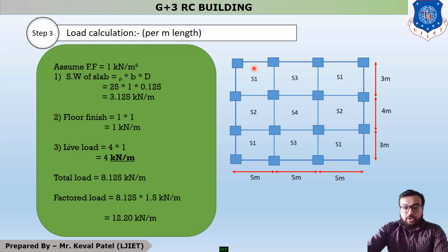So you can see that whenever we provide our main steel in this direction, your main steel is discontinuous on this side, but our main steel is continuous on this side. Okay, similarly, whenever we provide our main steel in this direction, it means in vertical direction, our main steel is discontinuous over these edges, but our main steel is continuous over these edges. It means your main steel is discontinuous over two edges, which are these two edges.